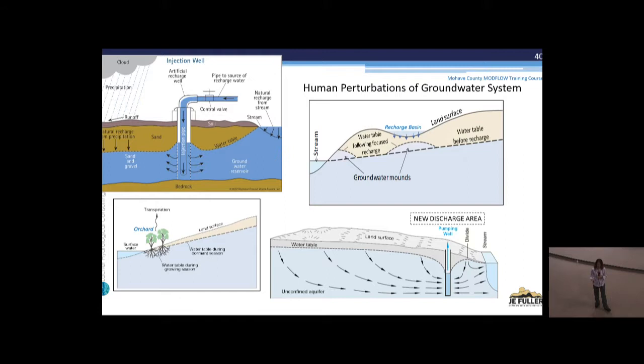And if it dries out completely, you can start getting upward gradients in the upper few feet. So that means if you wet and dry, and you only have a little bit of water, you could lose all of it in the soil zone. And it may just evaporate back out again. You have to have enough persistence and volume to break through that unsaturated zone and set up a downward flux, and overcome those evaporative forces at the surface.